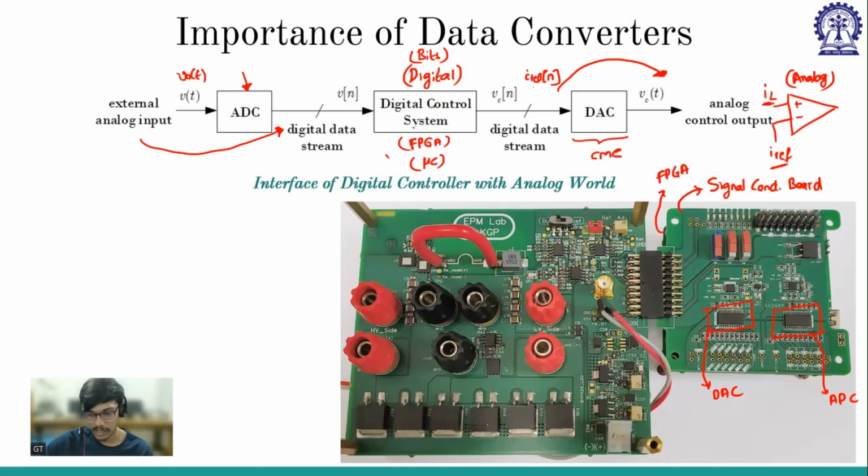So this connector is connecting the signals between these two boards, right? So whatever analog signals that we are getting will be fed into this ADC as input. Now this ADC output, these are the digital signals, which go into the FPGA, and these signals are coming from the FPGA back to the DAC, and the DAC is giving our analog output. That is how the communication is happening.